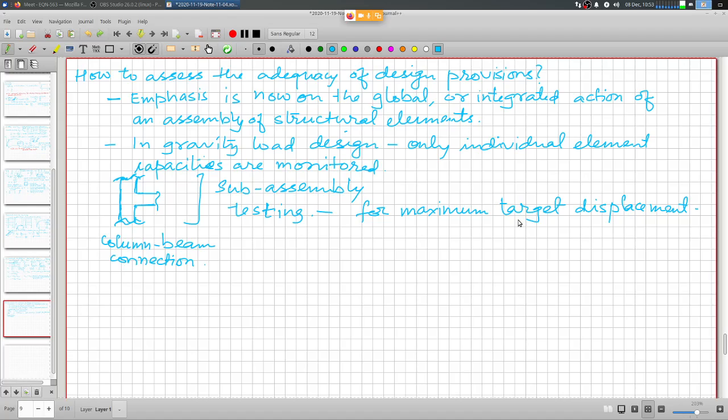But what we are doing here, what I explained, is that we need to develop very high confinement details so that concrete can sustain much higher strain, and it can generate reasonably large curvature ductility, so that we can get a reasonably sustainable amount of global displacement ductility that can be harnessed for inelastic deformation to withstand very severe earthquakes, which may occur only very rarely, right?